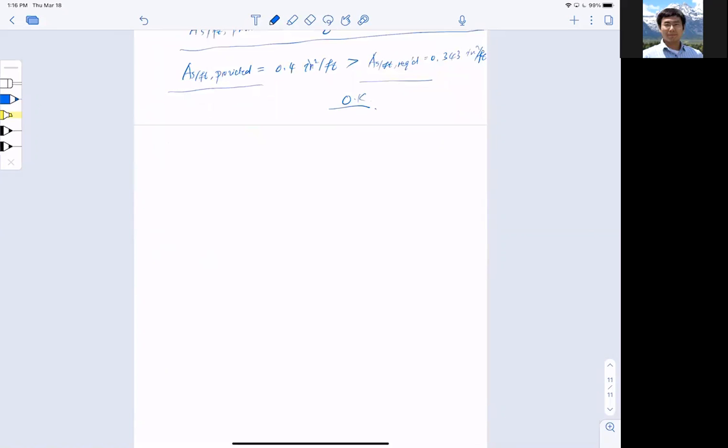But in terms of flexure, it's a lengthy process. We again have to confirm that it's yielding and tension controlled, because we assumed that phi equals 0.9. So we again have to find a, which equals As Fy divided by 0.85 f'c b.